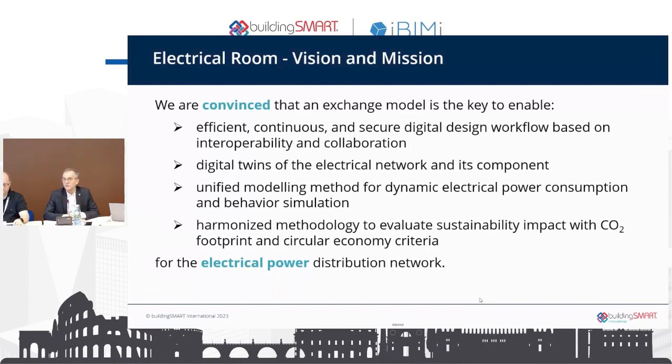At the end of the construction, the ambition is also that we have a digital model. We were speaking yesterday of a digital twin, horizon 1 or 2 or 3, but we need something digitally machine readable that represents the electrical network within the building, with all the relationship with the building. Where is my switchboard located? How do I control the light? Which is related to the space and the type of rooms and things like that. So that is about the electrical network and all the components that we need to have inside this data model.